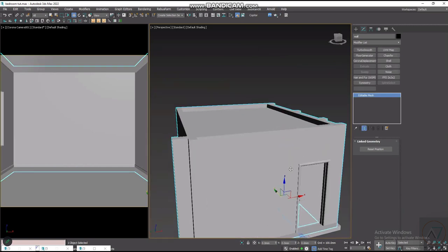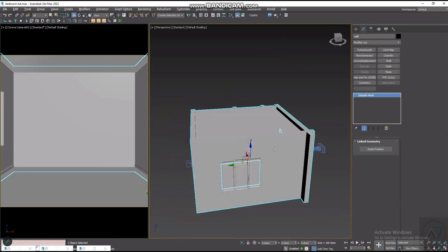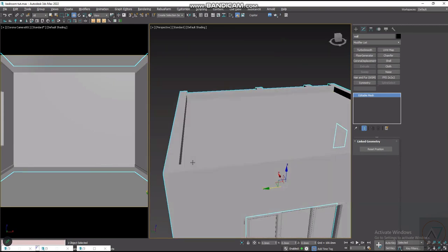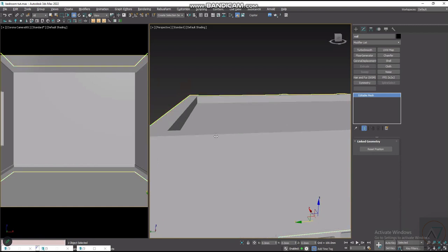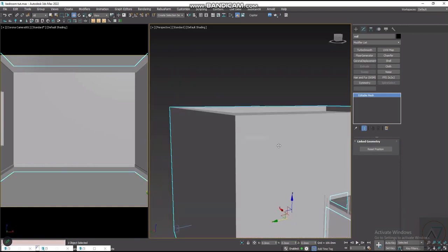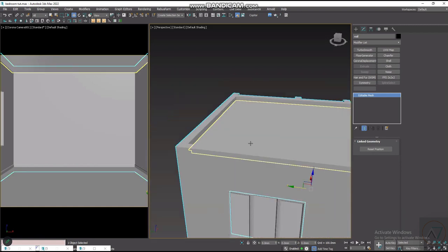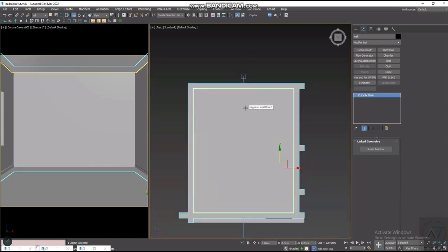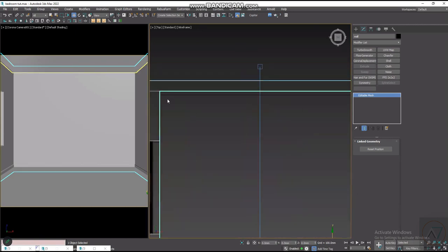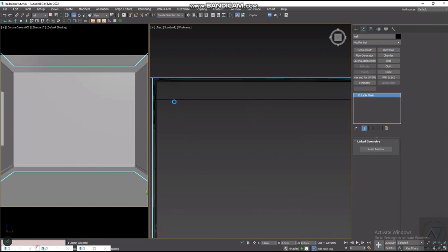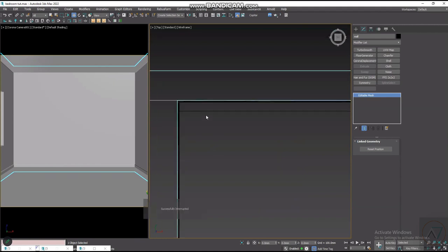So now, like I said, we are creating artificial lighting for our ceiling, because I have a recessed part here. We have to create a line light. To create a line light, I'll go to top, then click on F3 to give me the wireframe. You can see this part is the recessed part, and this line here. It's dark, but it's auto saving. Don't mind it, it's auto saving. You can escape it if you don't want to, but there's no time. Escape, you can see successfully interrupted.